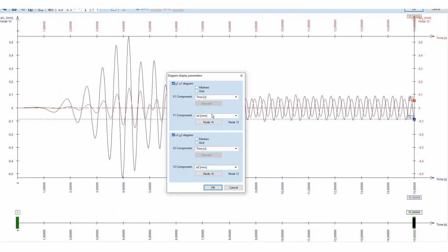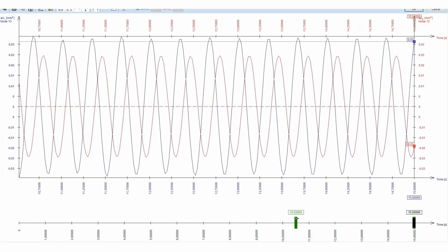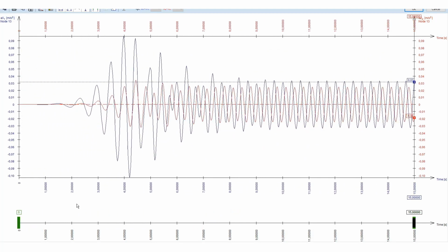The accelerations can be used to evaluate the structure and to determine if the vibrations are causing discomfort to the people inside. For example, as per ISO 2631, we can determine the maximal allowed human exposure time, or we can check if the limit of a given exposure time is exceeded and the structure fulfills the requirements or not.